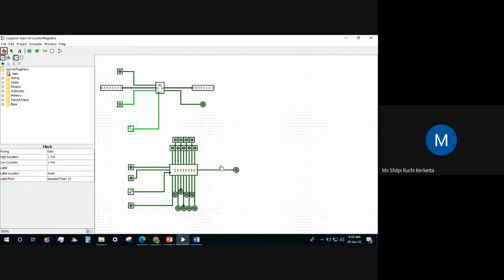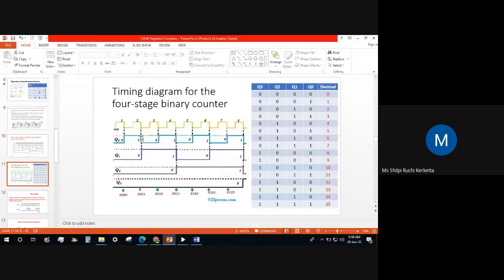So we will see this 8-bit binary counter. Here 0 is for up counting and 1 is for down counting. Here 8-bit numbers are there, and here we are using D-type flip-flops, which are positive edge triggered. Okay, so with every 1 it is changing, but our circuit is opposite. It is negative edge triggered, so with a 0 it will change.